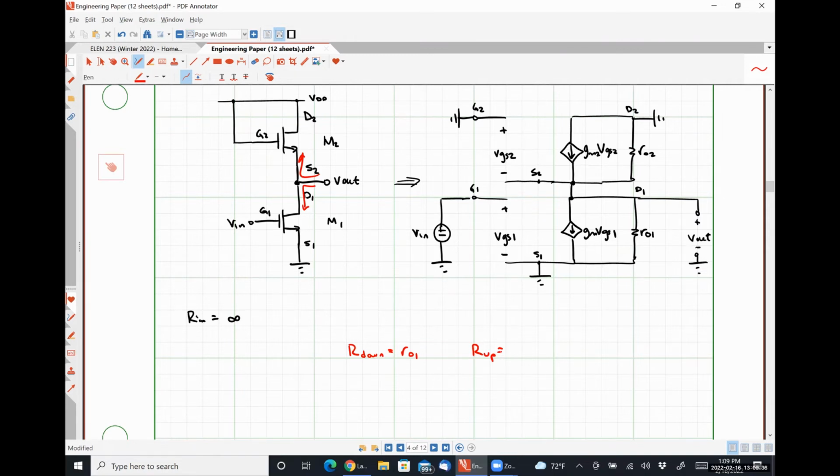Okay. Why is it harder? VGS is not 0. Absolutely right, which means this guy right here is no longer an open circuit. So we have to take into account what's going on. So the current flowing through this element, this dependent source, is gm VGS2. Can we all agree on that? It's literally written right there. That's the whole point of that dependent current source.